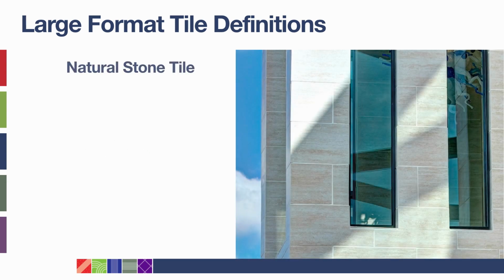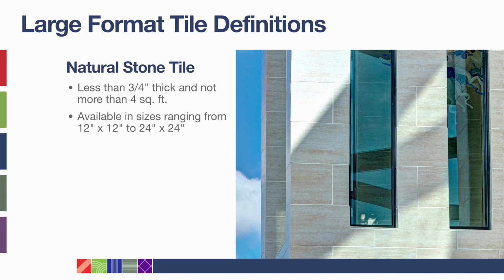Similarly, natural stone tile is available in sizes ranging from 12 inches by 12 inches to 24 inches by 24 inches. When less than 3/4 of an inch thick, natural stone tile must be adhesively attached for installation.